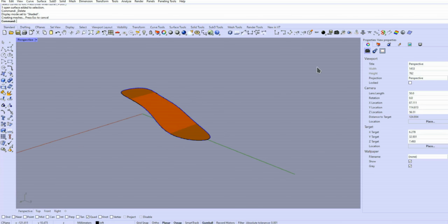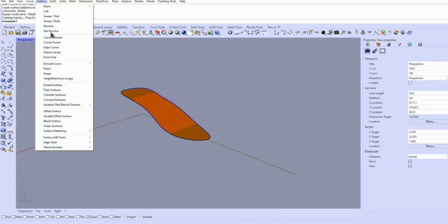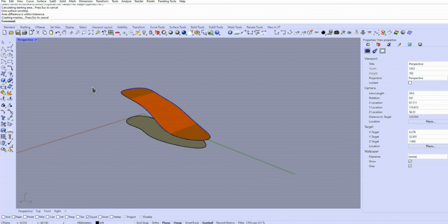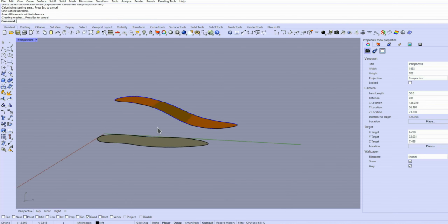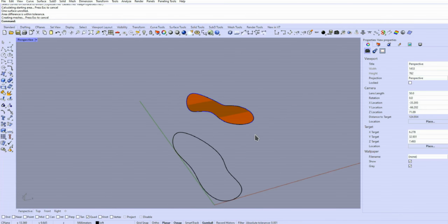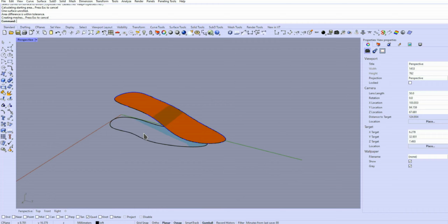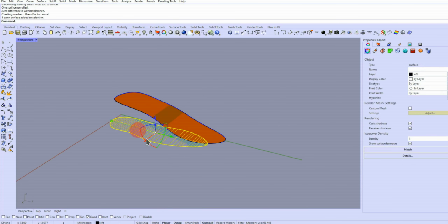This surface is developable. Set explode no, and as you can see, we can get a flat version of this surface, which will be necessary for the next operations, but we'll talk about it later. We can change the color of the flattened surface.